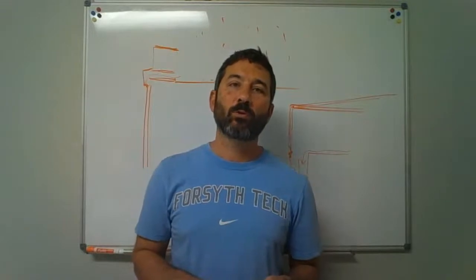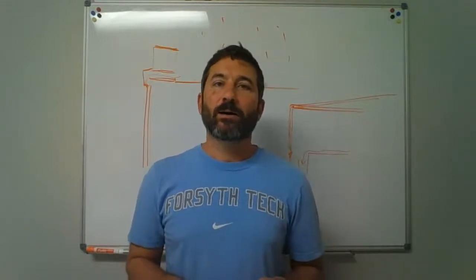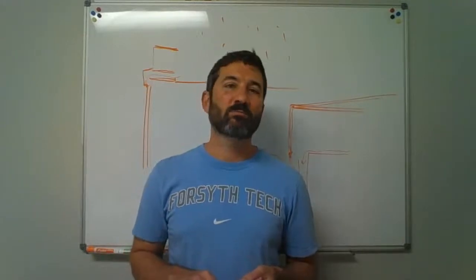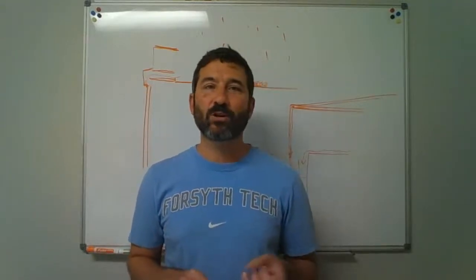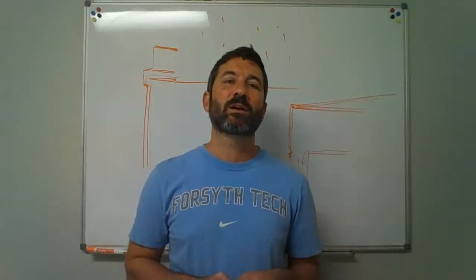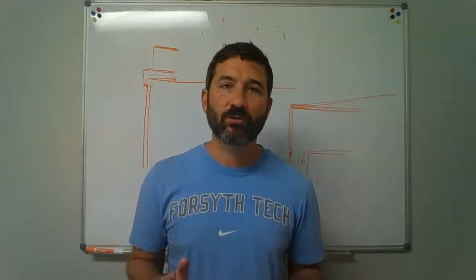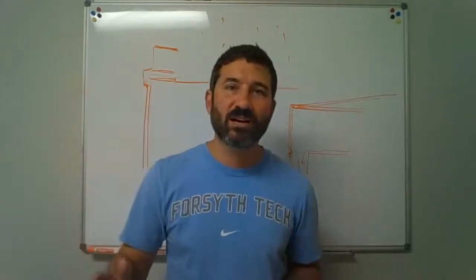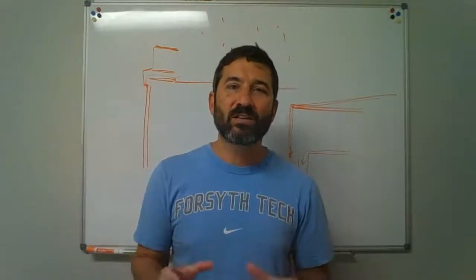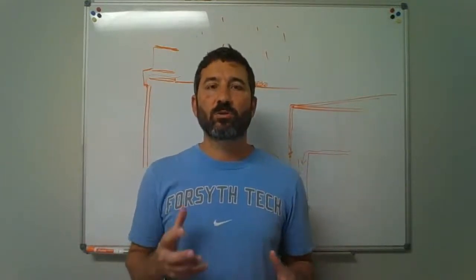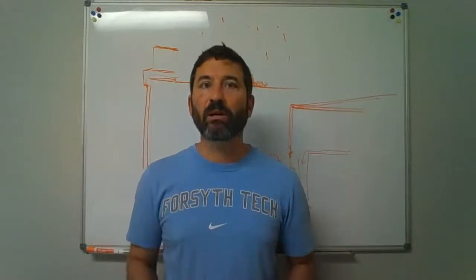Well, I would rather you know what the minimum slope requirements are on pipes. I want you to know what the maximum distance between trap and vent is. I want you to know what minimum size traps are. I want you to remember what the minimum DFU values for all the different fixtures are. I want you to know how far I can run a vent at its minimum size. What are the minimum vent sizes for all these different fixtures? That's the information that I really want you to apply and stick to your memory.